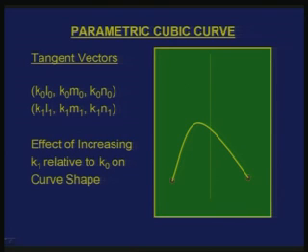So one can say that in a geometric form, the input one has to provide is the start point and end point. Either I can give the tangent vector with the magnitude, or direction cosines which are multiplied with a scalar value, k0 and k1.